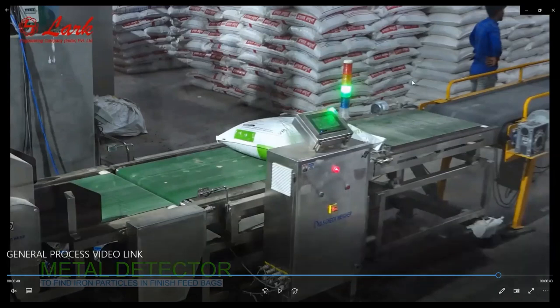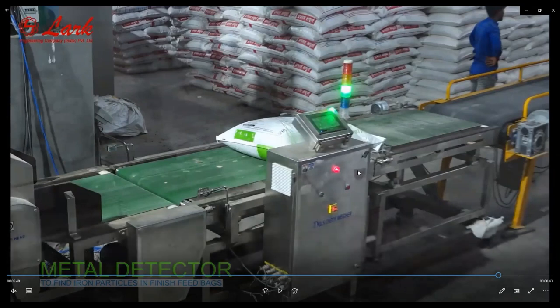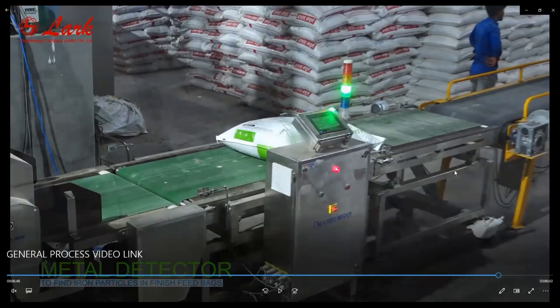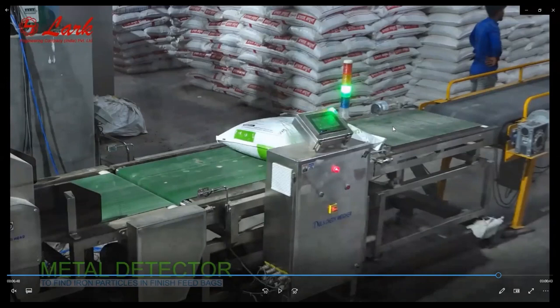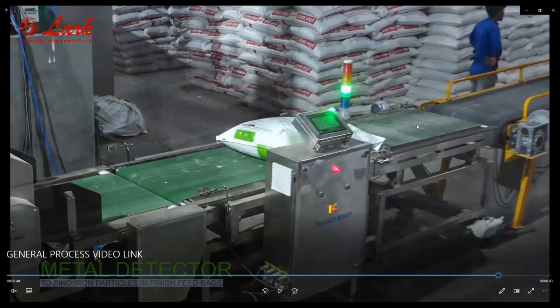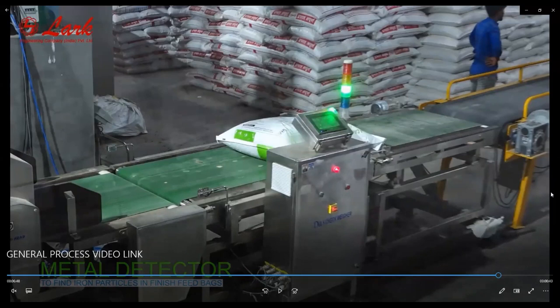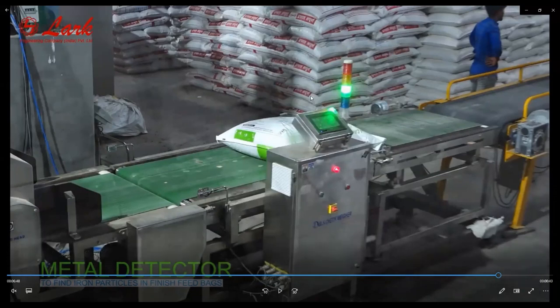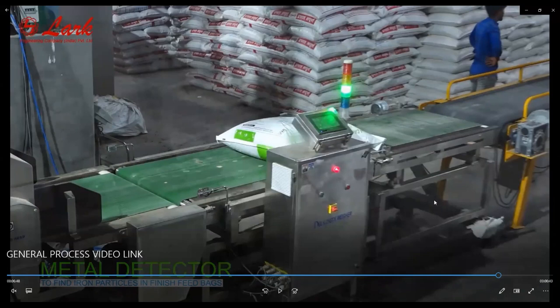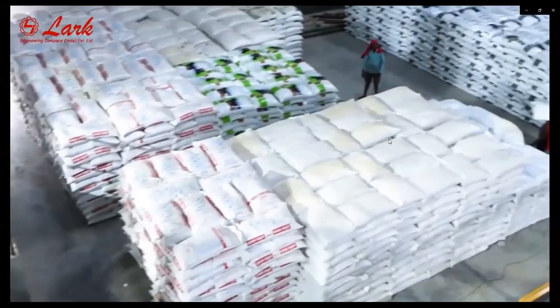So what we can do is place one continuous weigh machine after the auto bagging. Otherwise every fifth bag has to be randomly checked manually to see that the auto bagging is running properly. That costs a person, it is manual work, and it often gets skipped. To control that, we can add one continuous weigh machine at the bagging machine. The bag will pass along this conveyor over this platform. If the weight is not within the tolerance of the set weight, it automatically stops the conveyor, and the platform has pneumatic cylinders. The cylinders will open, this conveyor will tilt up, and the bag will be moved aside so that we can check it. So this is a very important thing in auto bagging that we can add to our existing machines and feed mills also. So this is a complete idea of the feed mill process.